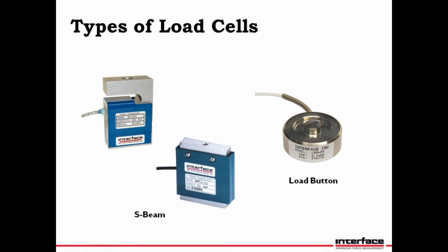All right, moving on to the next slide. Starting from the left going right, that's our S-type load cell. It's also got a center mounting thread. It's got great accuracy for a low cost. Below that is our SMT. This is also an S-type load cell, but it offers overload protection in both tension and compression.